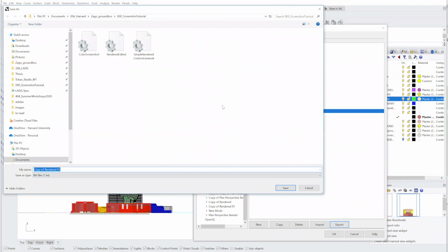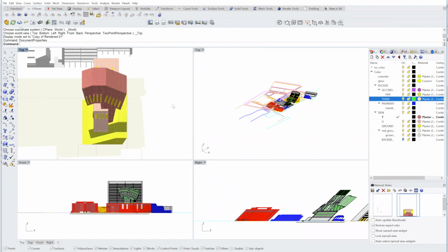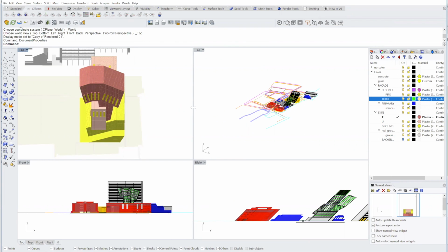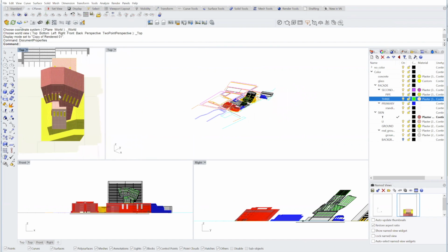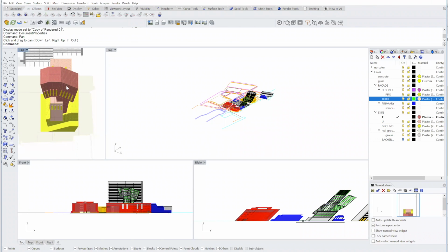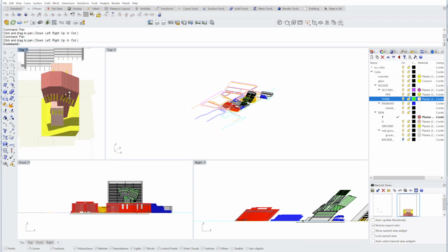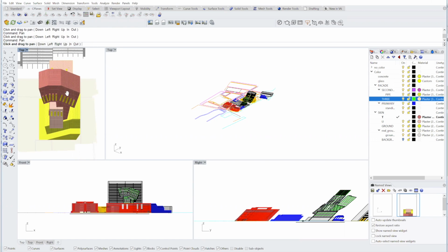So if I'm happy with this viewport, I can go to the top and click display modes on the left, go over, click my viewport, and then save it as a .ini file. If I want to import this onto a different computer, I can just import that .ini file. It will save after you close Rhino, but if you want to switch machines, you might want to save your file. So to make this in the vertical aspect ratio, I'm going to actually use my Rhino screens and drag them so I can kind of frame it. If you just press Control and hold down the right click, you can also zoom in and out slowly.